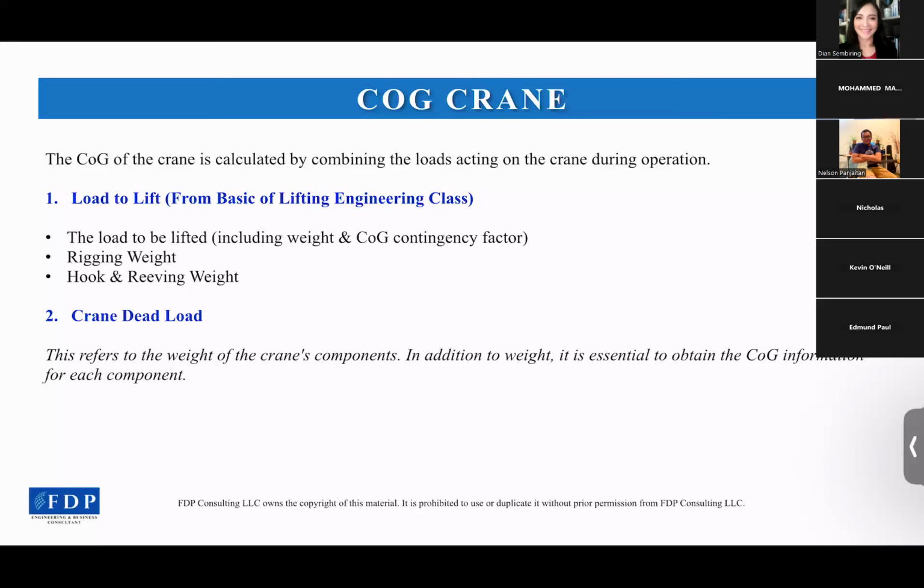But in some conditions, for example, if we use a suspended superlift counterweight, the load will no longer be realistic and leads us to an unrealistic superlift requirement. And if we use an unrealistic superlift, maybe during operation it will be okay. But if it happens many times, it could damage the track of the crane or the superlift connection.